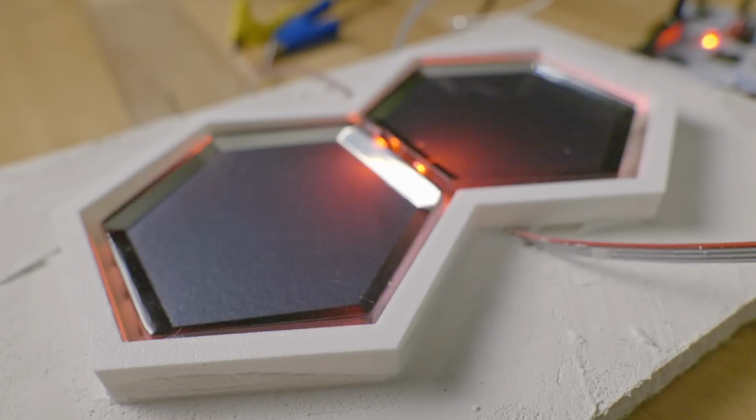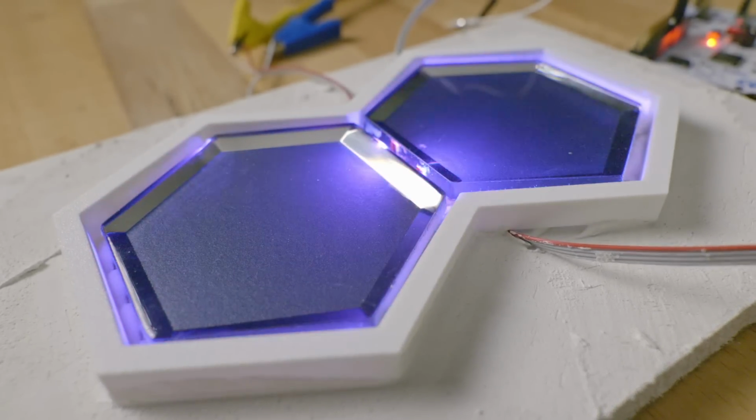This is what I'm doing with the PY32 in my Tile Backsplash project. Here, I'm using the internal ADC on the PY32 to digitize a microphone signal and communicate the peak value back to a main processor. I need about 250 of these, so for a personal project, I just really can't afford to use anything more expensive.